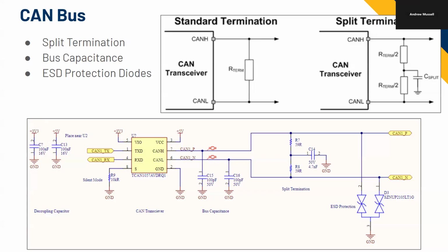Like you have ESD to protect from high voltages, but is there ever a case where you need to fuse, like on the CAN bus, in case something pops with high current? Yeah, that's a good idea. In terms of high current events, you would put the high current protection on the input of your power network so that the power network can't pull too much power. Or maybe you also put fusing on the output of your power network so your power network can't source too much power.